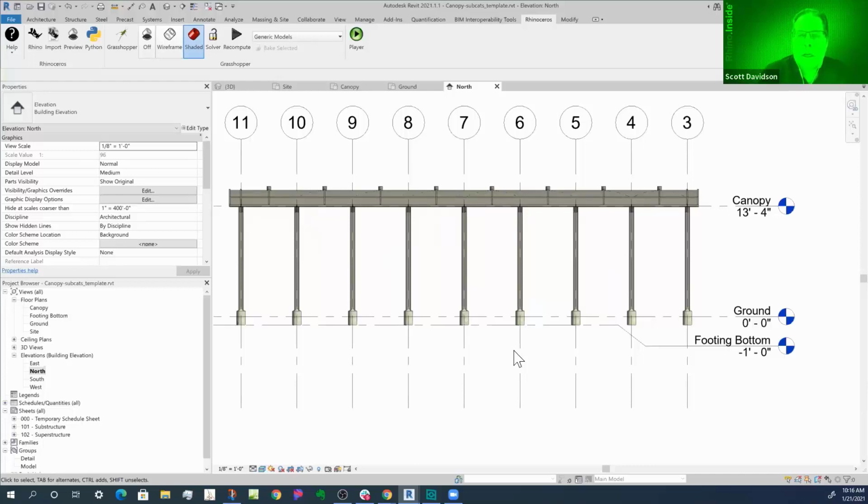And of course that can change over time. You might, for instance, have floor plates that are going across and are official, but you might still be working on the facade. So the facade might be direct shape objects, which you're going to just use temporarily until the facade kind of settles down in the design. So there's a lot of options here for your workflow.